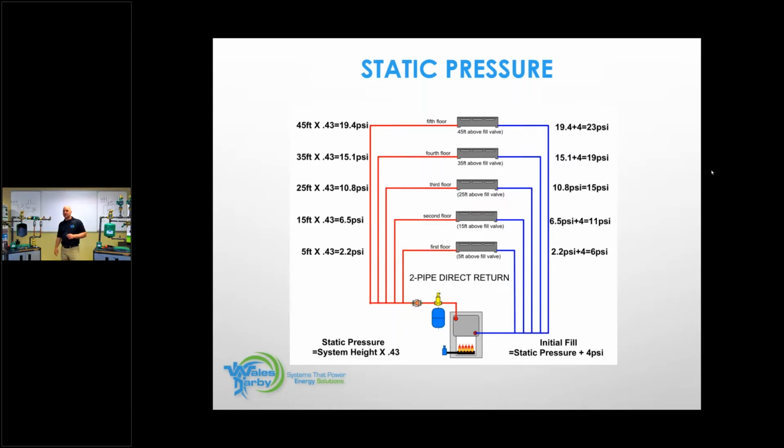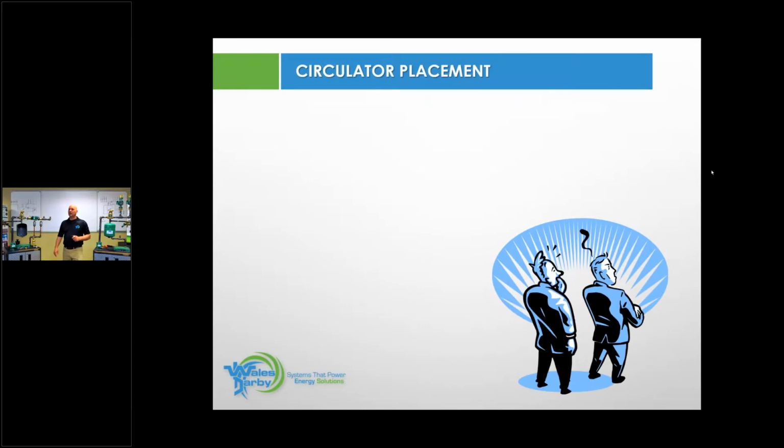Keep this handy. Just keep this in mind. This could be on root cause troubleshooting, whether it's this week or next week. Be alert. So I talked about circulators not pumping into an expansion tank. A circulator system, a zone valve system. Is the location of a circulator important in a hydronic system? The answer is yes. Pump away from an expansion tank, there's the question.